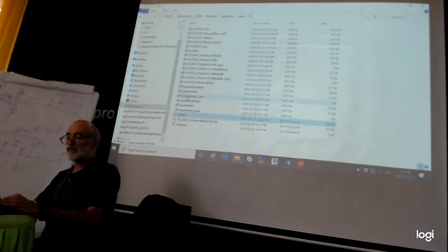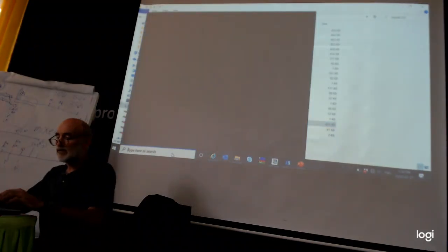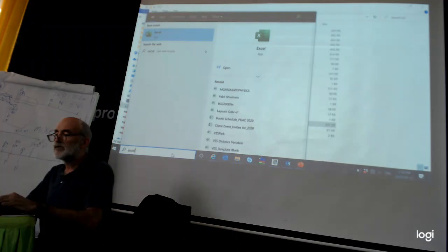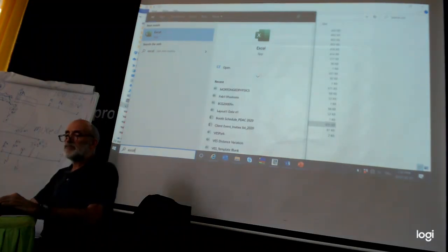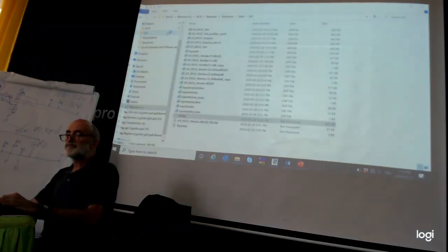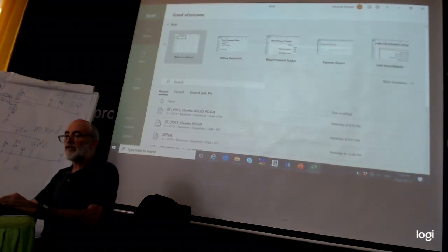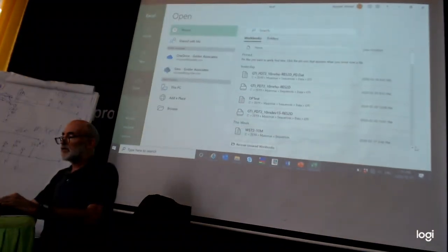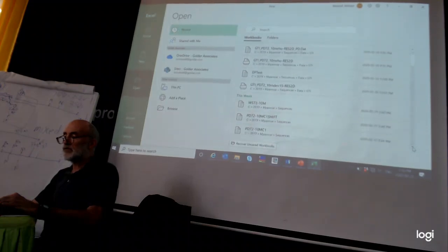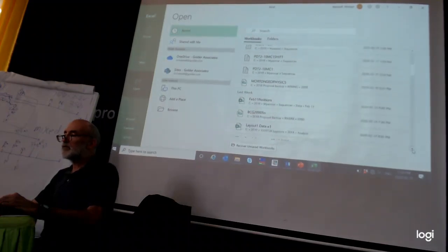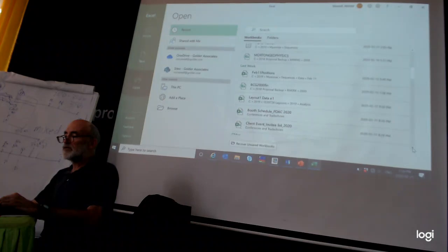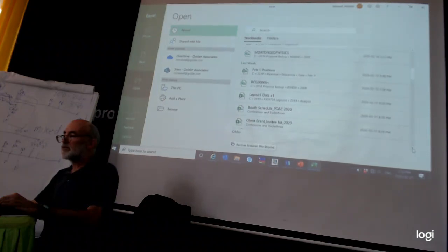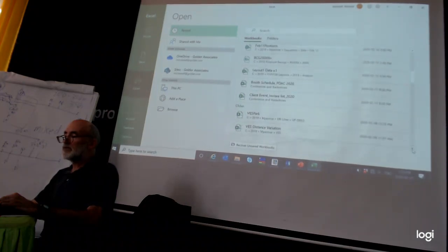Even though this is a bit more confusing, the reason we talk about this is that in theory, pole-dipole can see deeper compared to Wenner-Schlumberger or dipole-dipole. Usually we use Wenner-Schlumberger and dipole-dipole. So this is for more special cases where you want to see deeper.